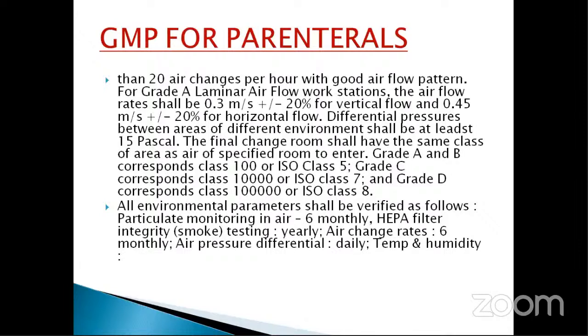Differential pressure: you know that between areas of different environments, say from B grade to C grade, C grade to D grade, or B grade to A grade, whenever you are changing the gradation of clean room, there will always be a pressure difference. And the pressure difference is 15 Pascal. Why is the pressure difference maintained? To keep away the dirt particles from the lower grade room. So which one will be the higher pressure area? The cleaner room will be the higher pressure area, because it will not allow air to come into that area from the lower grade clean room.